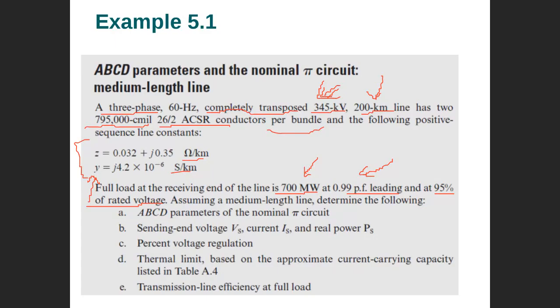So this will be P minus jQ, not P plus jQ. If you're asked to find the reactive power, you can determine it as minus jQ. So the load does not absorb reactive power. The load injects, or delivers, reactive power.